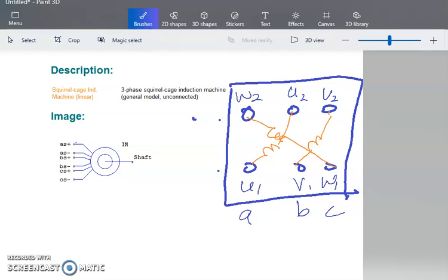For delta connection, usually we have a metal plate which interconnects all the upper and lower wires and will connect into your line, red, yellow, blue, and red, yellow, blue. This is for delta connection.